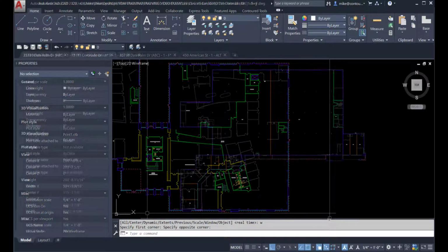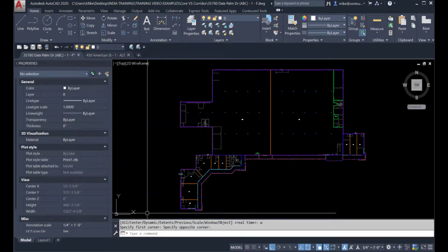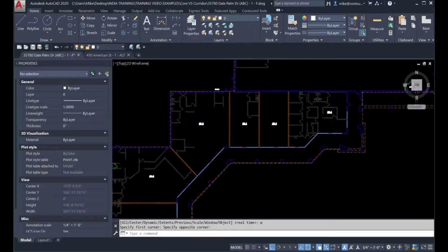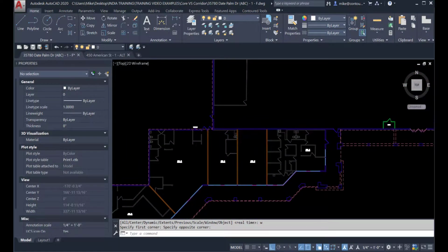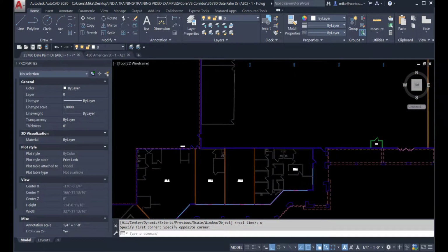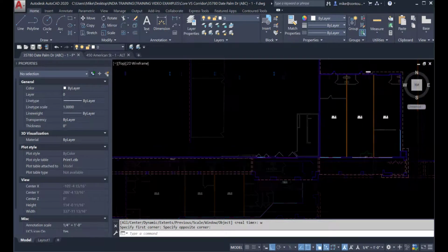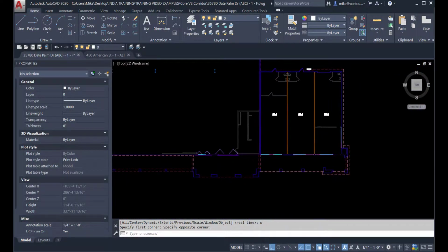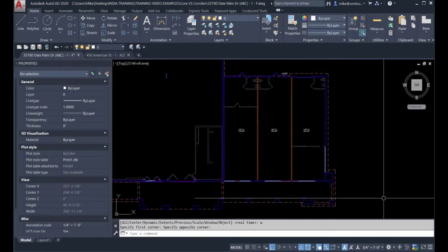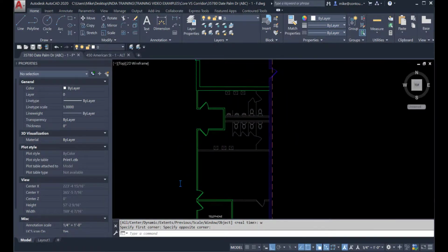Since corridors can be tricky and depend on the layout of the building, always use your best judgment to determine corridor layering. Here's an example of a building that does not fit the office type scenario. There is no clear corridor inside the building. This is because access to each suite is from the outside. This is more in line with an industrial or retail type building. In this situation, each tenant has their own private service rooms. This would include restrooms, electrical, and telephone rooms.